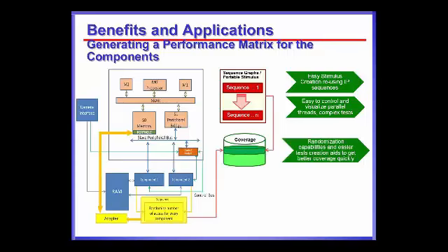And the additional benefit of using SystemVerilog to create these instructions is that on the fly we can randomize it also, and it will support seed-based randomization. So we can create multiple configurations within the same test, and that will help to close the verification coverage, right?